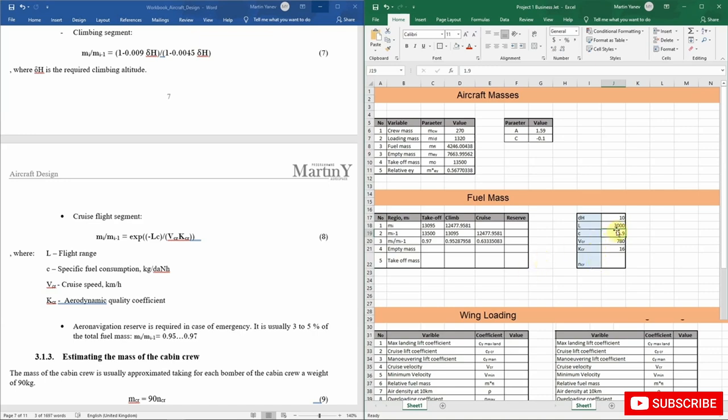Okay, so finally, having all these values here, we estimated that for 3000 kilometers, our cruise fuel coefficient will be 0.63. So finally, the fuel after the stage will be equal to 12,477 multiplied by 0.633, and we're getting for our mass after the cruise flight to be equal to 7,902.